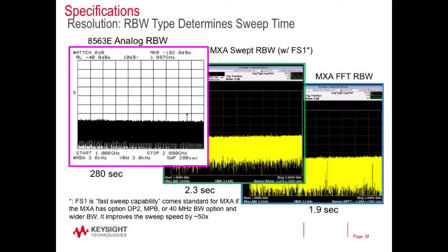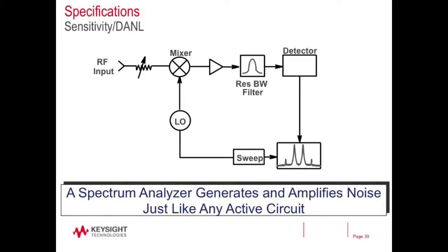All right. So aside from phase noise, one of the other important concepts on a network analyzer is what you call dynamic range. That has a few implications, but generally it falls into a couple of categories. Can I look at a small signal in the presence of a large signal? The other thing is, how small a signal can I look at?